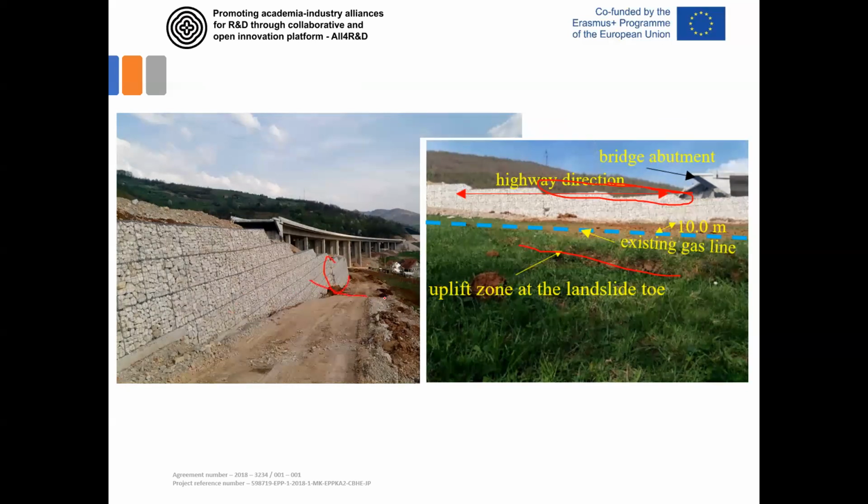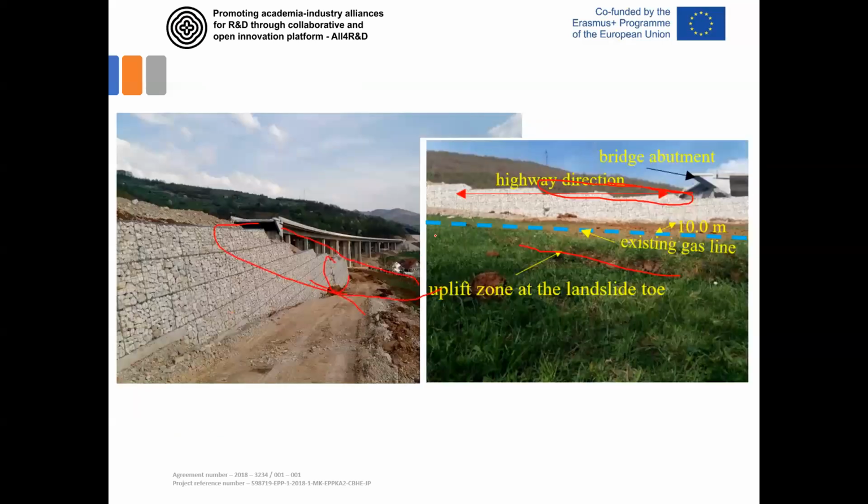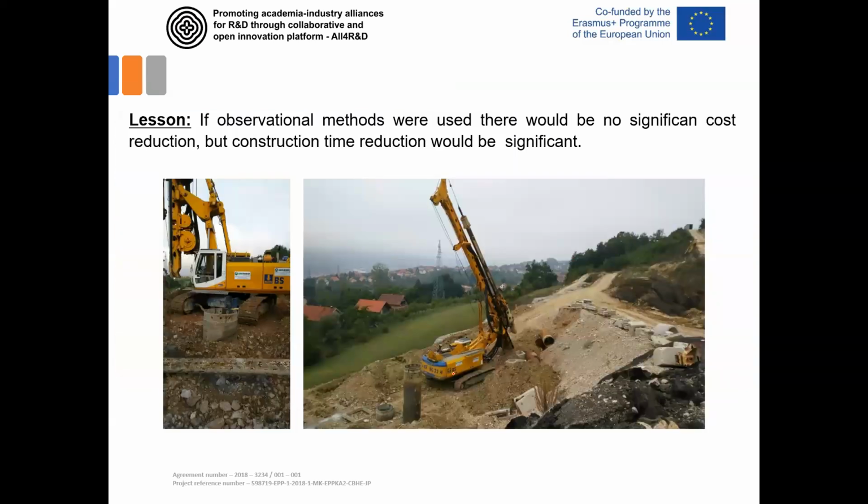You can see this line, you can see all this dropping down, and the global stability of this embankment was the problem. What happened later? This was all removed. A deep foundation was introduced, 2 lines of bored piles of large diameters with a capping beam, and as a retaining structure, a concrete wall was built up to construct this.